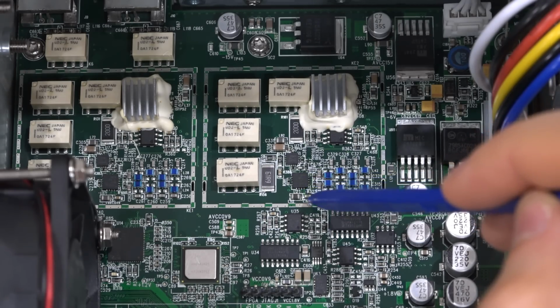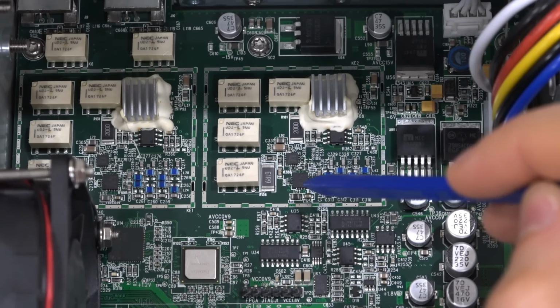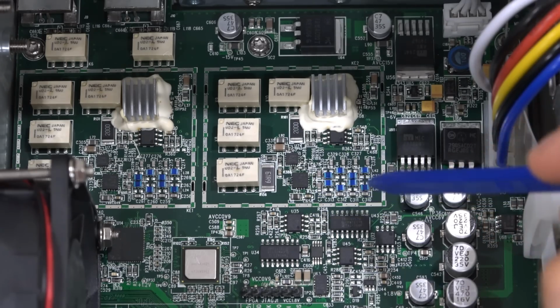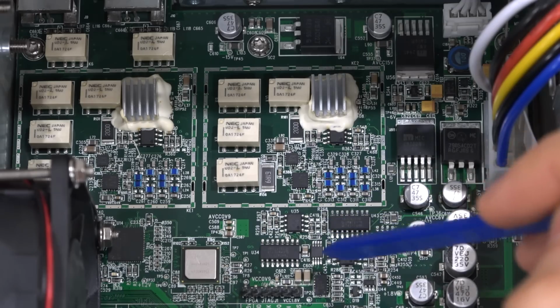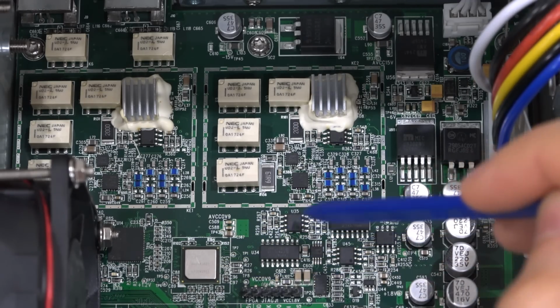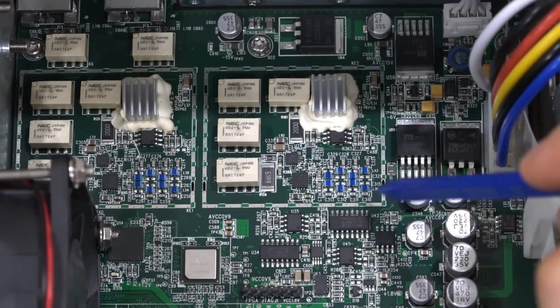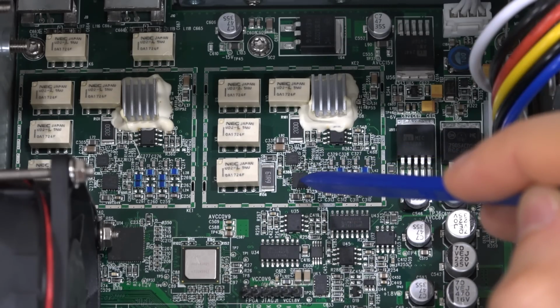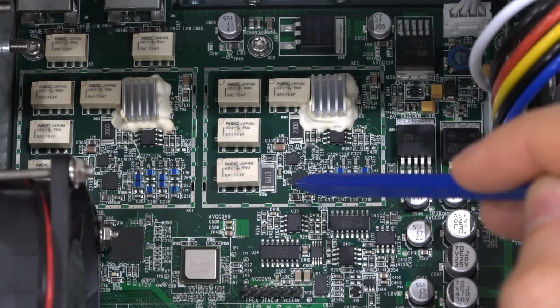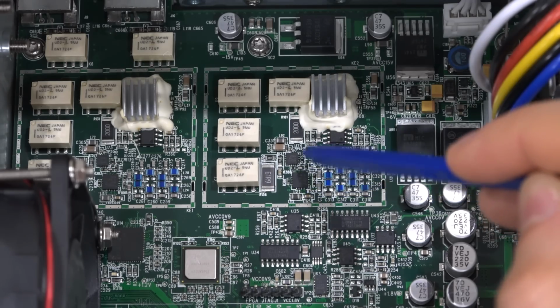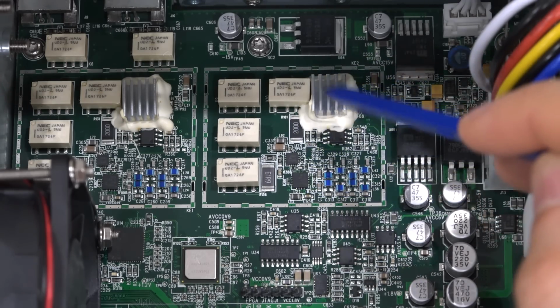It has several different options. You can actually bypass to the outside and filter and then come back into the chip, and I believe this is what this section over here is. So the signal coming from here goes into here differentially, can go out, get filtered, go back in, and then come out single-ended. Now the single-ended output can then be dealt with by putting it through an amplifier, and I believe that's what is underneath this heatsink over here.